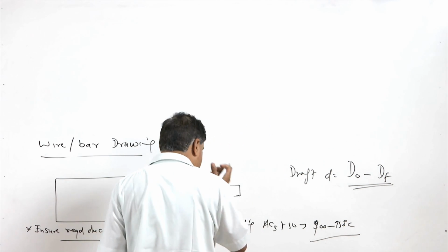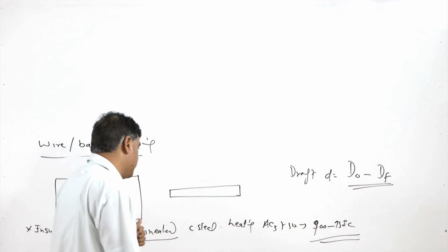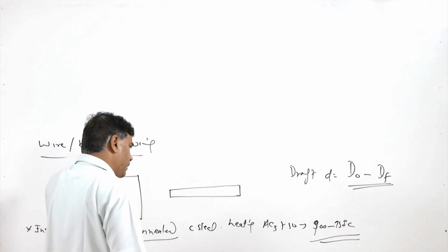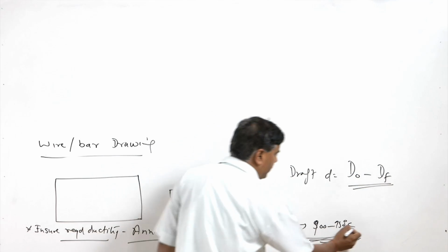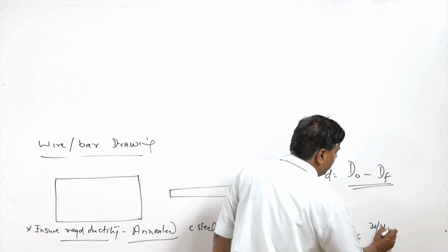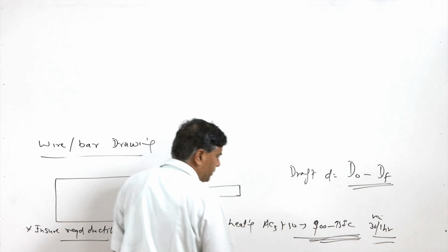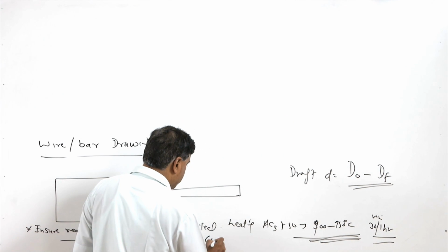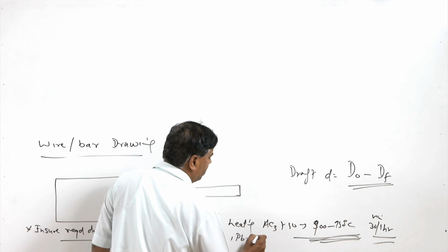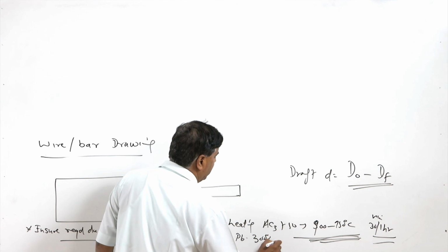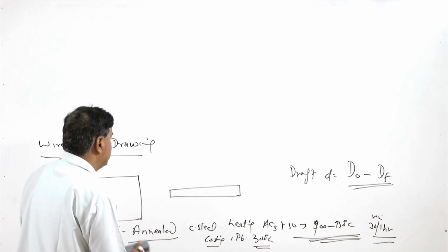Depending upon the carbon content in the steel, there can be a very wide range for the annealing, which will be used for inducing the ductility. And after heating at this temperature for say 30 minutes to 1 hour, depending upon the diameter, it is subjected to cooling in a lead bath, at about 300 degrees centigrade, so that it induces the required ductility in the metal.